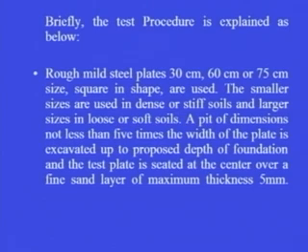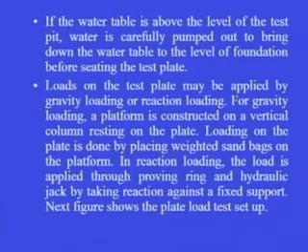A pit of dimensions not less than 5 times the width of the plate is excavated up to the proposed depth of foundation, and the test plate is seated at the center over a fine sand layer of maximum thickness 5 millimeter. If the water table is above the level of test pit, water is carefully pumped out to bring down the water table to the level of foundation before seating the test plate.